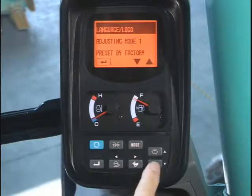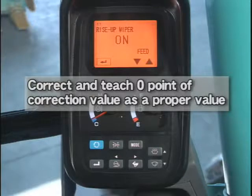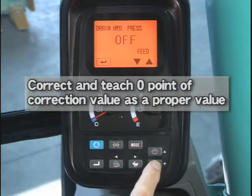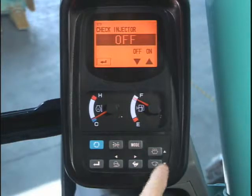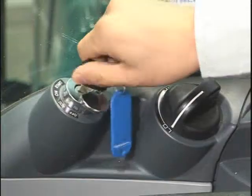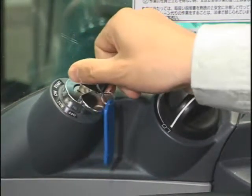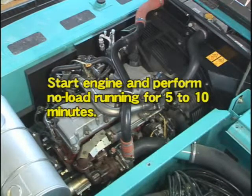Next, correct and teach 0 point of correction value as a proper value. By operating the gauge cluster, display the service adjustment 1 and set on at the items of check injector. Then, start the engine and perform no load running for 5 to 10 minutes. Then, you can completely finish the injector calibration.